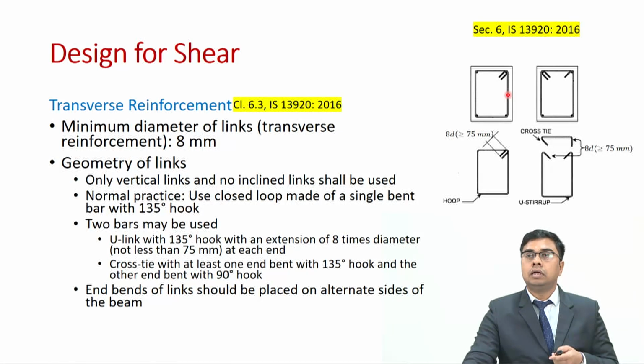So, especially for site engineers, you need to look at the site as well. Whenever there is a tying of reinforcement, at that time make sure that your stirrups are having closed loop with 135-degree hook like this.